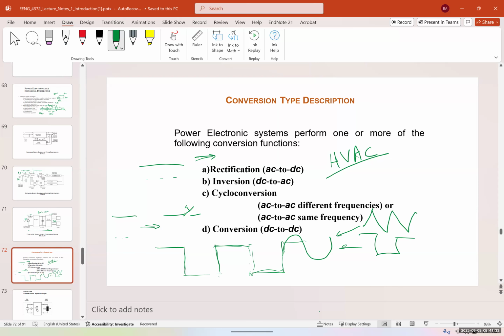But for any AC motor connected to this, because the signal suddenly moves from positive to negative without a smooth transition, we get different harmonics, like the first, third, and fifth harmonic, and I'll explain this later. That creates extra pressure on the motor. It's going to heat up the motor, and it's bad for the motor.